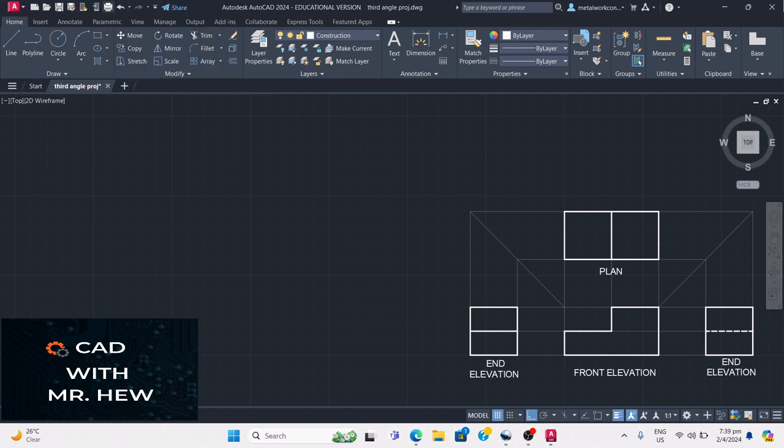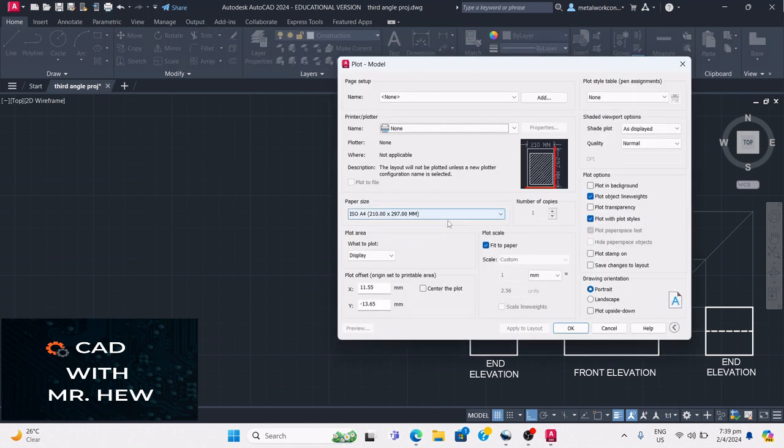So we come up here to plot, click the plot icon, and here we have the paper size A4, right? So we are using the metric equivalent size paper that is similar to the letter size paper, okay? So the equivalent paper, which is a closer size to the letter size paper, the measurements in millimeters is 210 millimeters as a length, right?